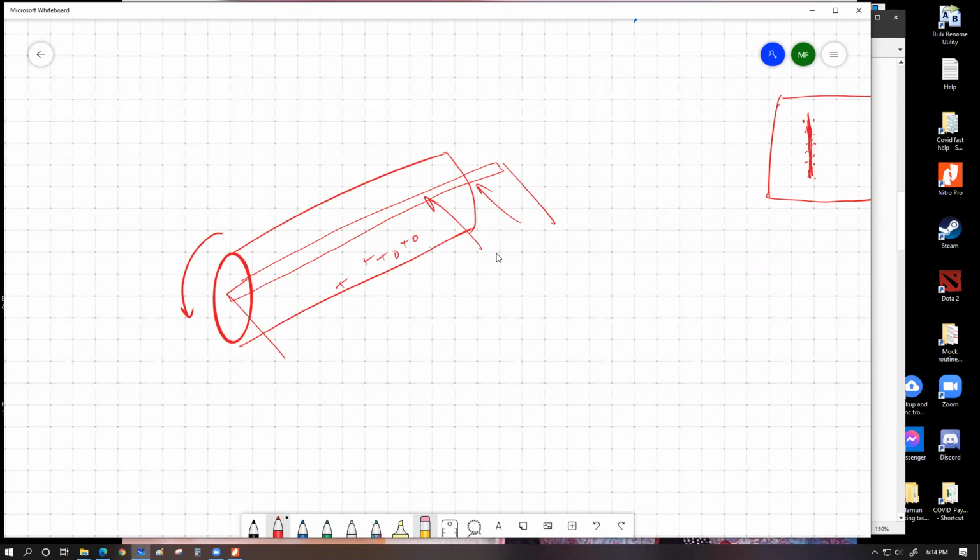If you wonder how we got the positively charged air, it's very simple. It's very similar to the nozzle that we have seen for electrostatic spray painting. We are flowing air through this channel, and this metal piece is connected to the positive end of a battery or a supply. Now, when this happens, a certain thickness of the selenium coating becomes positively charged, because as the positively charged air particles hit the selenium atoms, the selenium atoms give out their electrons pretty easily. Sorry, they themselves become positively charged by losing an electron.